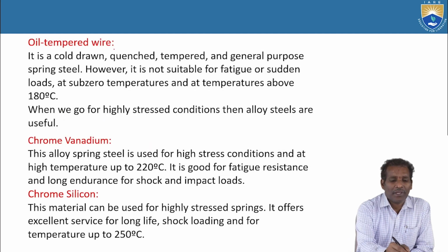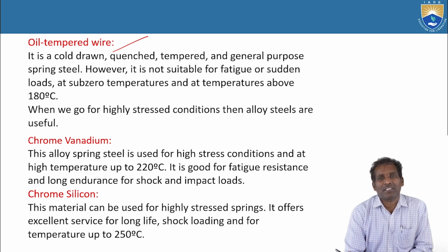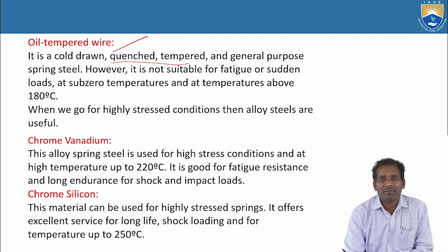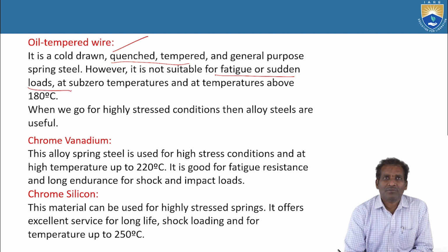Next, oil tempered wire. It is a cold drawn, quenched, tempered, general purpose spring steel. You already know these processes from material science: quenching, tempering, normalizing, annealing. However, it is not suitable for fatigue or sudden loads.